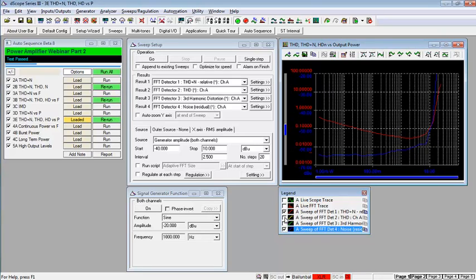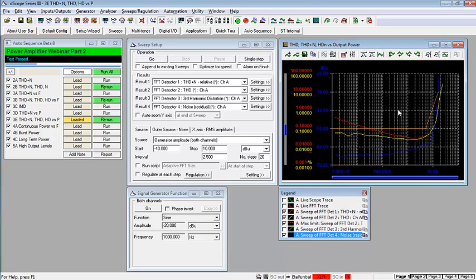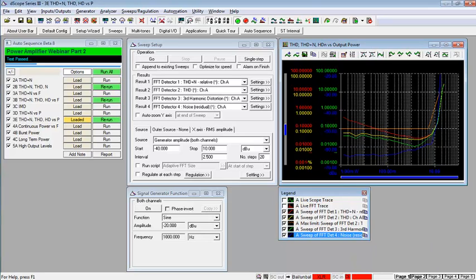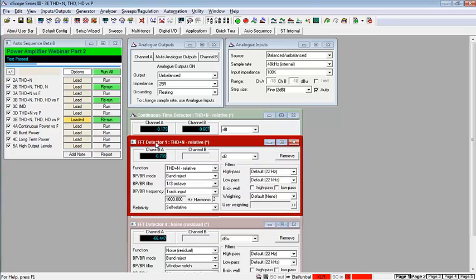So what is going on then? We've seen that the THD isn't responsible for this measurement failure, and we've seen that the noise isn't responsible for this measurement failure. So what was it? Well, I can reveal that 8 of you were correct, and you did identify the problem, and that is that when we calculate THD plus N, the most common way of expressing this is in self-relative dimensionless units. So quite commonly either dB or percentage are the main units that you would use to measure THD plus N. What does that mean?